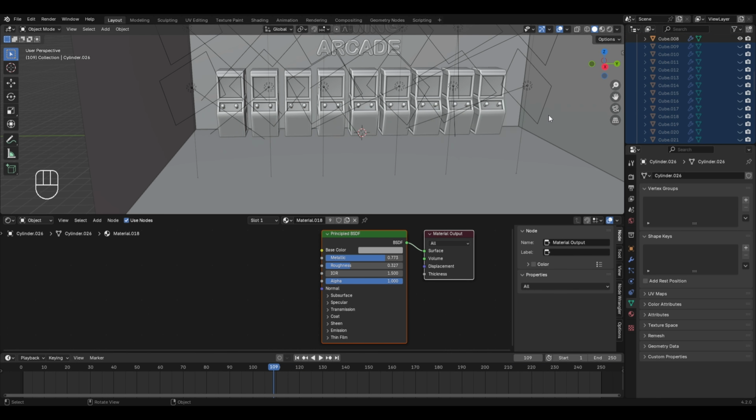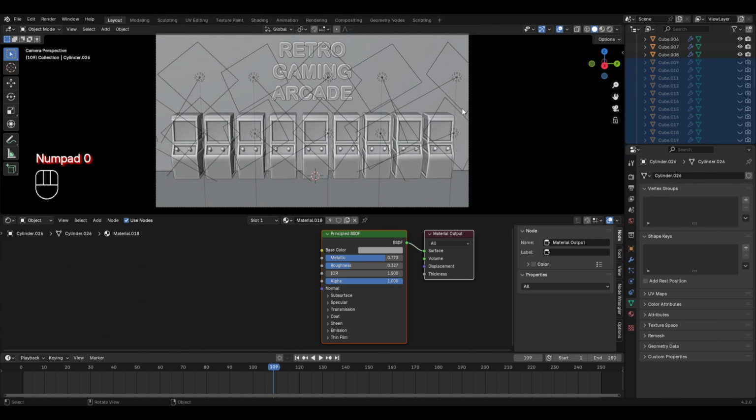However, they will still be visible in the final animation that we create until we disable these camera icons for the selected objects. And instead of left clicking for each of these individually, you can simply hold the left mouse button and drag the cursor like this. This will disable the camera icon for all these objects. After this, we are now ready to create the rendered animation.